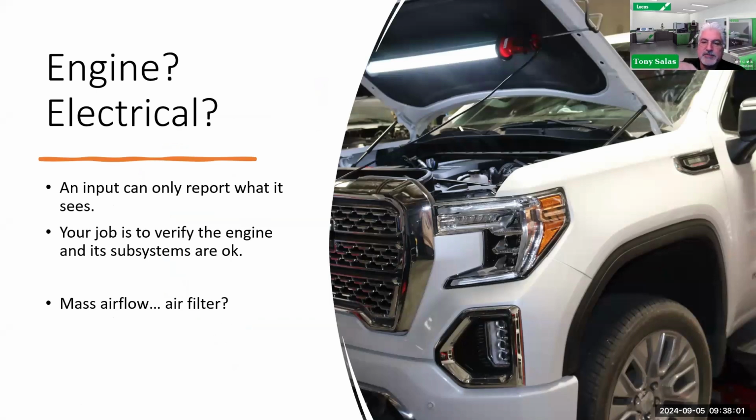So how many times have I taken, for example, I just did a 6.4, I took the MAP sensor out, and that MAP sensor was heavily coated with carbon. Same thing on a Duramax L5P. That can cause incorrect readings as well. So even though you look at a PID, if the PID's incorrect, it could be electrical, or it could be engine related, or it could be something around the surrounding area of that input, such as that sensor, that can be the cause. So always keep that in mind.